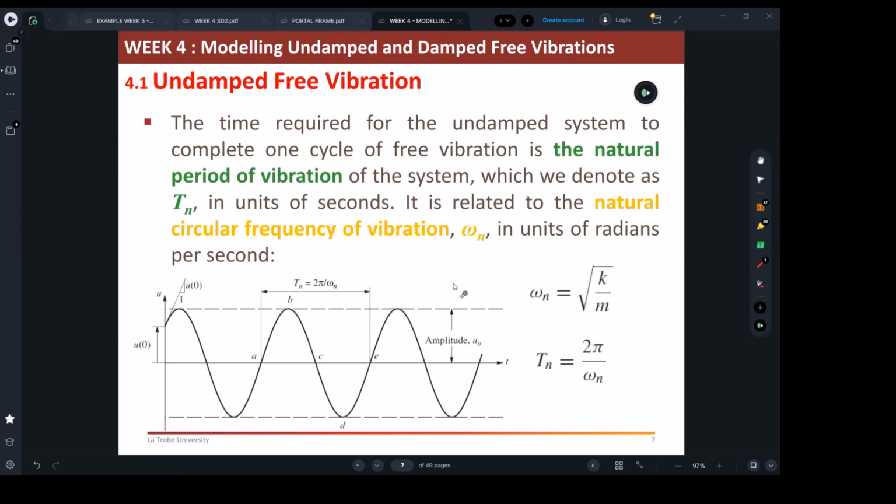If you find it's happening, then your building is sensitive, and you have to think about doing something to the building. Make your stiffness higher, and that will change your frequency. You cannot control what's coming from outside, if it was an earthquake, but you can control the building itself. Maybe we cannot change the mass of the building.